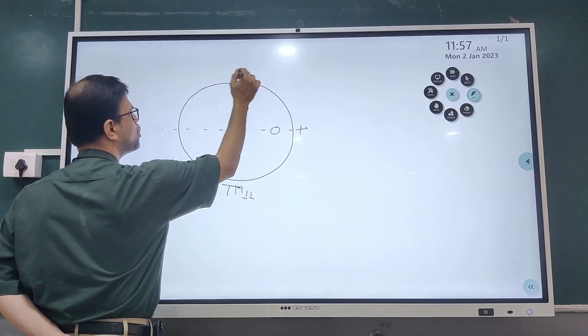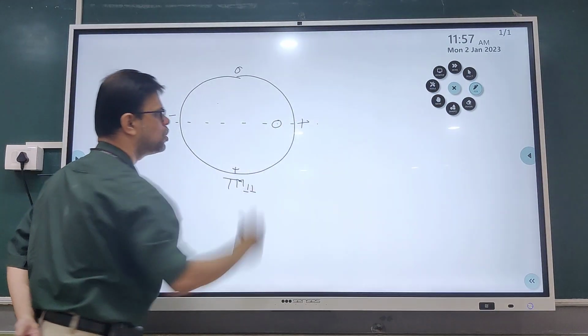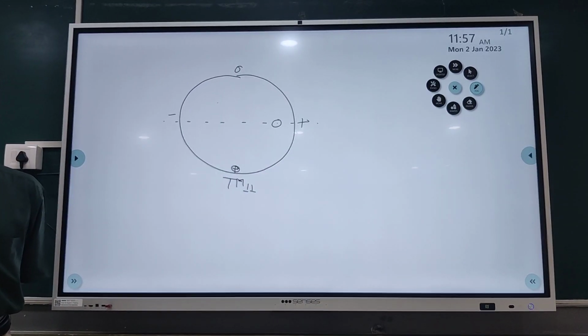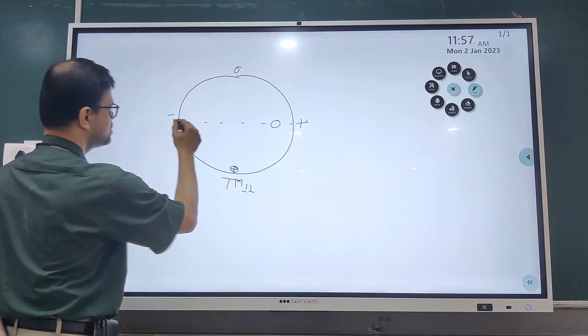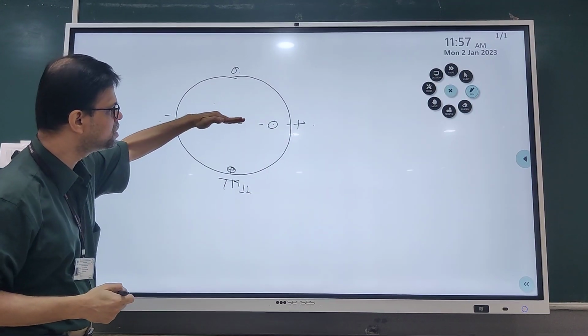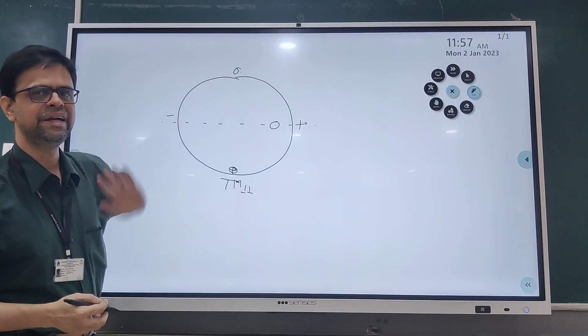So accordingly I will draw the field distribution. Now you will see, with respect to the coaxial feed, you have a symmetry because this is plus, this is minus, this is 0 and this is 0. So with respect to this center axis, or the coaxial axis, the fields are identical.